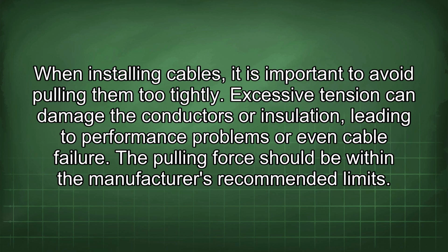When installing cables, it is important to avoid pulling them too tightly. Excessive tension can damage the conductors or insulation, leading to performance problems or even cable failure. The pulling force should be within the manufacturer's recommended limits.